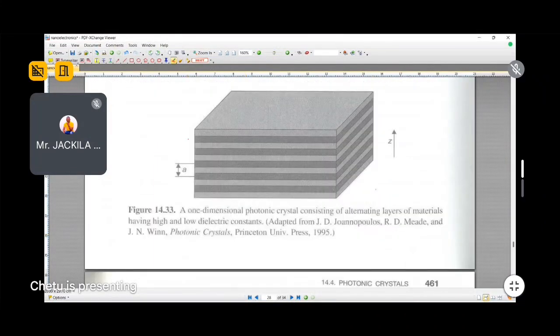And by solving the data available from that measurement, you can actually calculate the refractive index of individual layers. This means this device measures the overall refractive index, dielectric constant, and extinction coefficient of the entire material. Now, using the software and knowing the observed values, if you develop this multi-layer model, then this model can easily tell you the refractive index of each individual layer used in this.